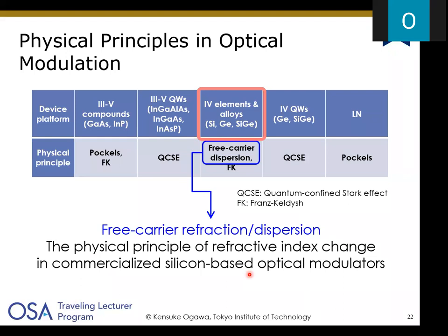And the other aspect is related to the phase shifters, the active devices, to control the optical properties of the waveguide by electrical signals applied from electrical drivers or signal processors. In crystalline silicon, the crystal has an inversion symmetry. So no electro-optic effect, the Pockels effect, is absent in silicon because of the inversion symmetry.